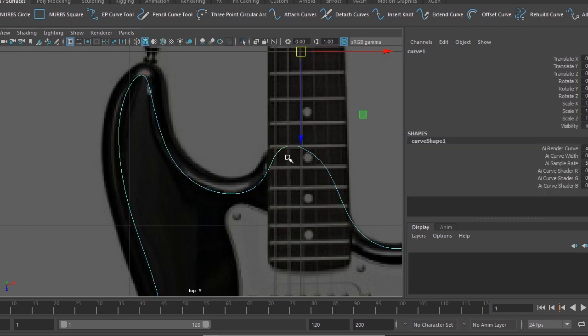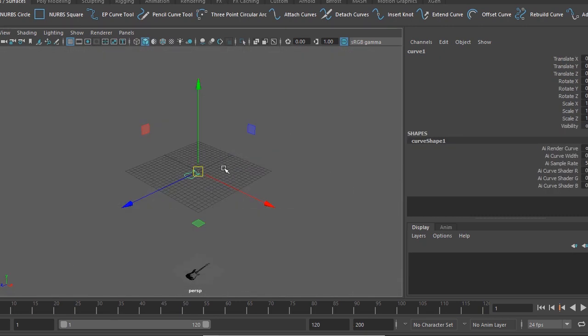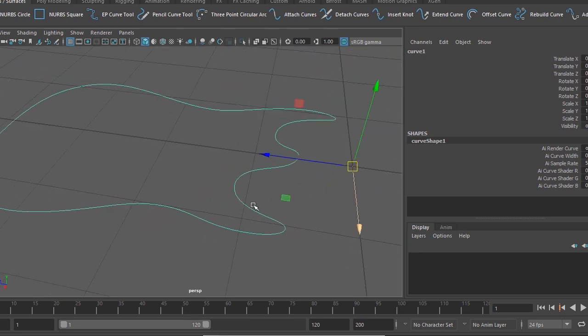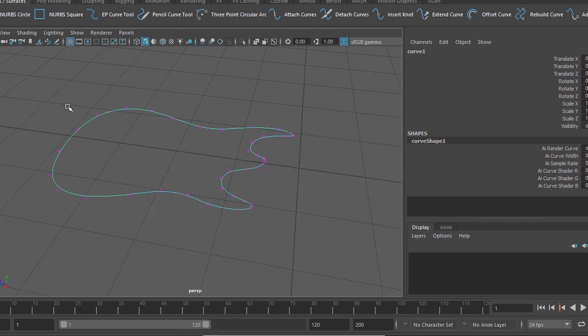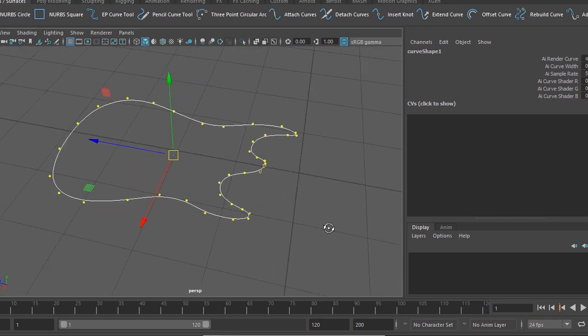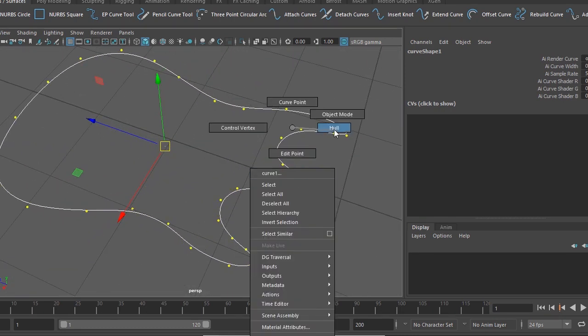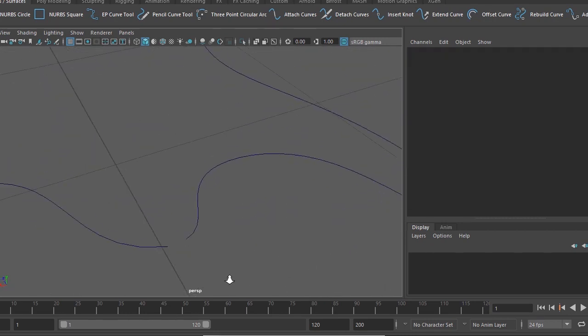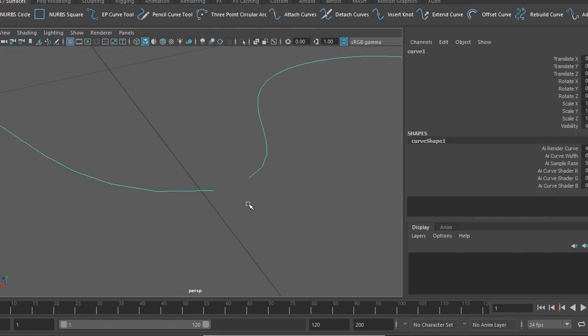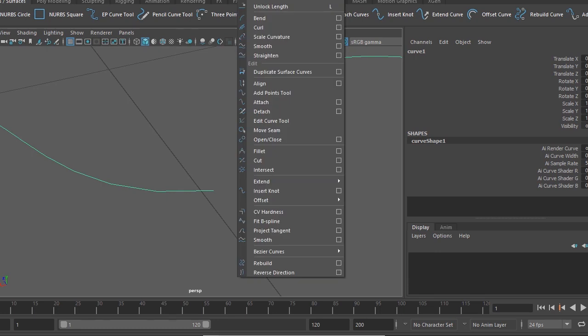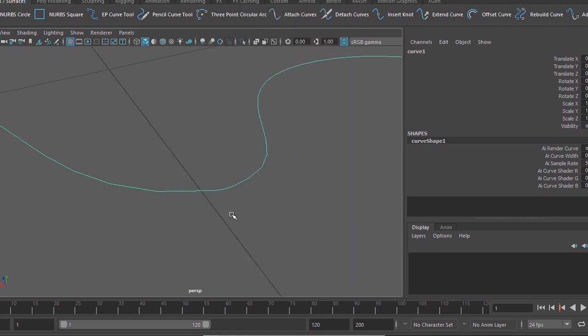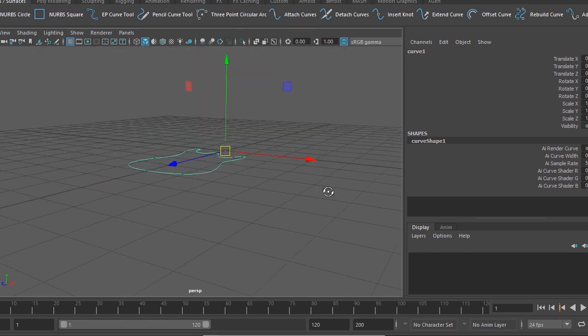So here this curve is open. You see I've created a curve, and we got some vertex points all over. They are almost equally distributed, looks good, but this is an open curve, so I need to fix that. So I go to Edit Curves and use an option called Open and Close tool. This will close the curve, and then we can create a model out of it.